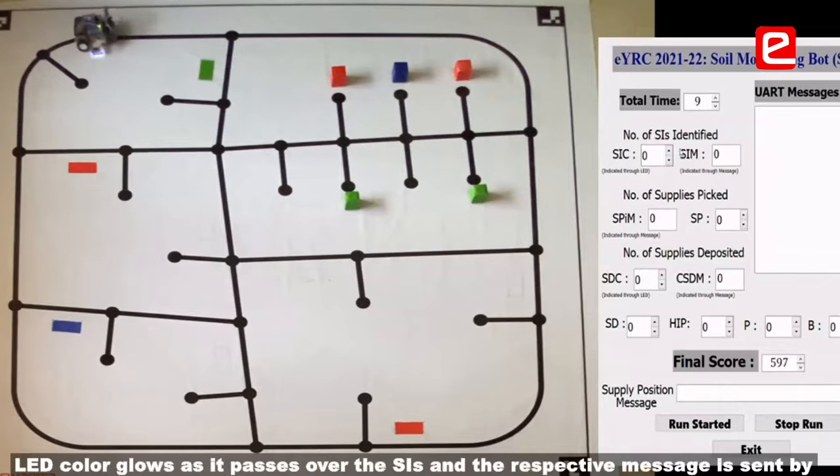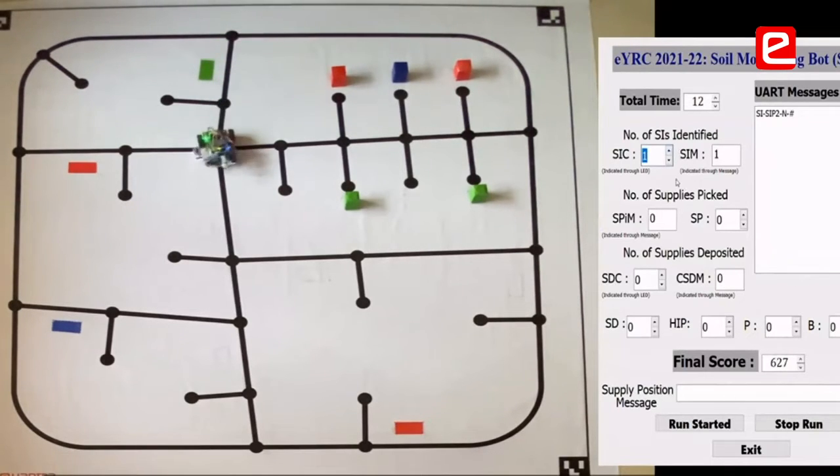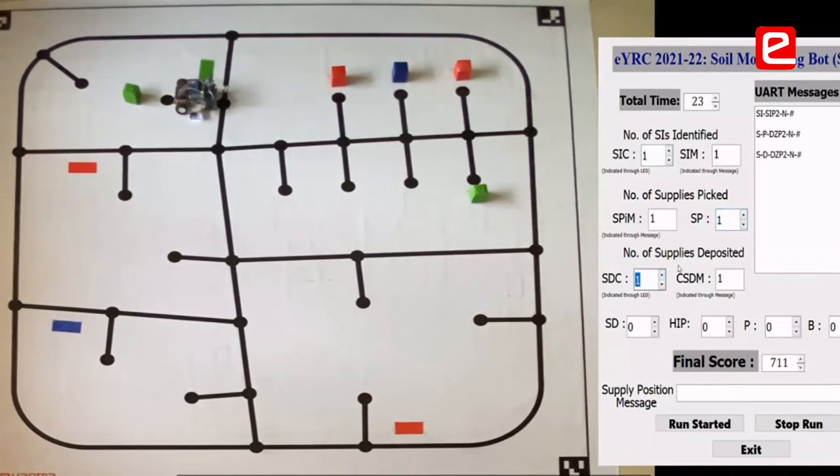Also, 2D arrays don't actually have support in Verilog. We were able to get it to compile for, say, 8 nodes, which I listed there. That 20 line code, the for loop array, was getting compiled when we had a set of 8 nodes. As soon as I entered my 37 nodes, it started causing all problems.